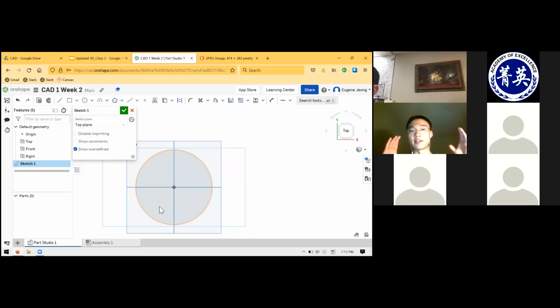It is at a specific location with respect to the origin of the sketch, instead of just floating off somewhere away from the origin, because if it's just floating, then that's a degree of freedom, right? It's able to translate with respect to the origin. So the reason I'm using the origin as the center is just so I get rid of those 2 degrees of freedom.